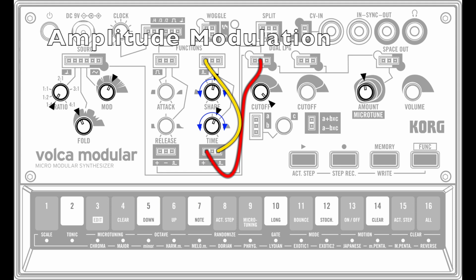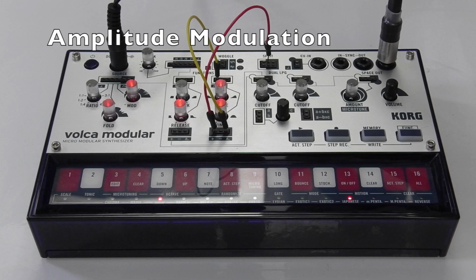This sound will play automatically when the connections are made. Remember, the carrier and modulator waves are always active, so as soon as a suitable signal is connected to the LPG1 level input, the carrier wave, which is connected by the default routing, will be heard at that volume. Adjust the shape and time controls for variations.